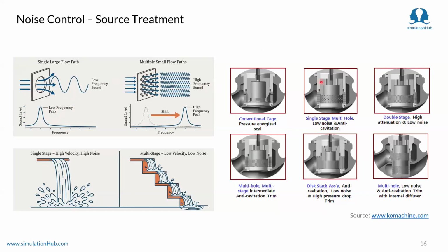So you can see on the right side, I pulled some examples of real valves and how they mitigate. From one of the manufacturers, it's mentioned single stage multi-hole. So this is what I was talking about, multi-hole. This is one methodology, and they've written low noise and anti-cavitation. So it is one way to fight or eliminate cavitation and noise as well.